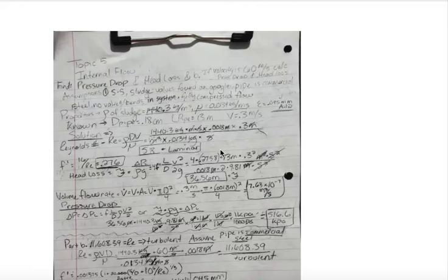Right away, we can calculate the Reynolds number using all the knowns, the density, diameter, velocity, viscosity, to get 58, which is laminar. With the friction factor being 16 over Reynolds number, we get 0.276. When we plug that friction factor in and all these other knowns, we get a head loss of 36.56 meters. Then, when you manipulate that head loss equation to calculate for delta P, you just multiply your head loss times your density times gravity, which gives you 516.6 kPa when your velocity is 0.3 meters per second.